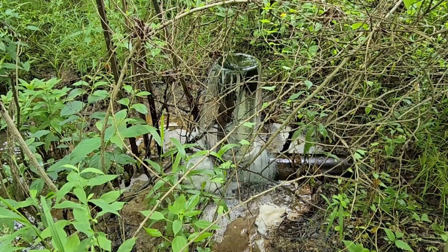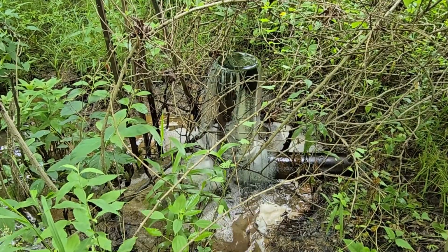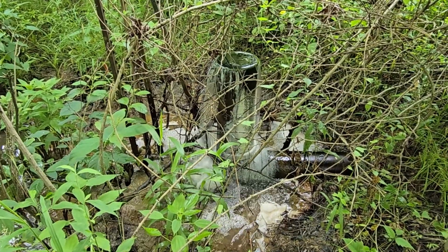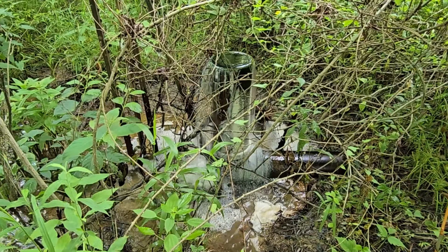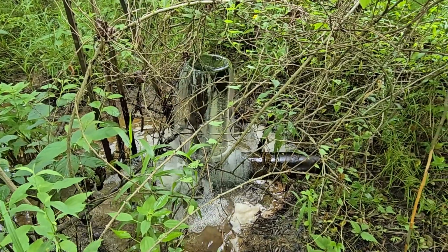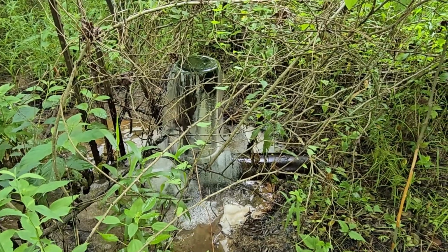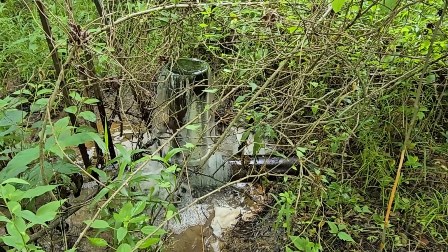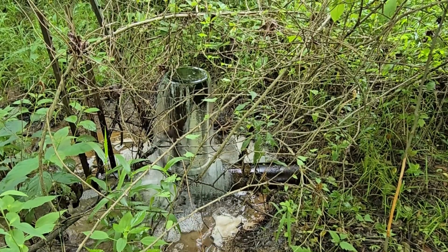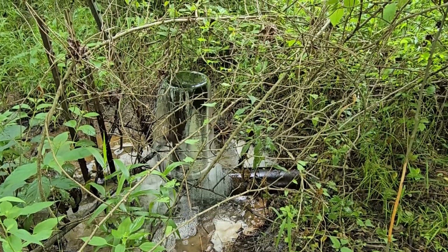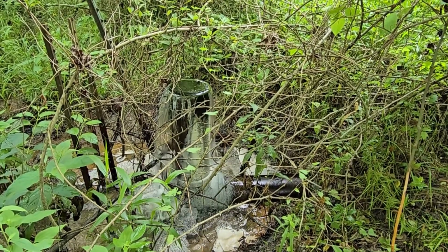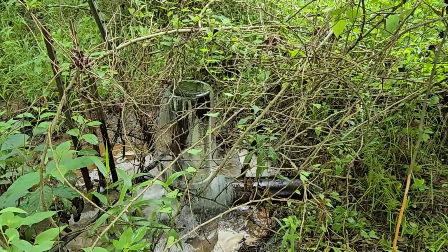Here's a simple and inexpensive water control structure that's combined with an overflow pipe that's been working for 27 years with absolutely no maintenance. The water control structure is located on the backside of the dam, and it's not in the wetland pool. We use sections of 8-inch diameter PVC Schedule 35 SDR gasketed pipes for the drain pipe, which was installed under the dam during the construction of the wetland.